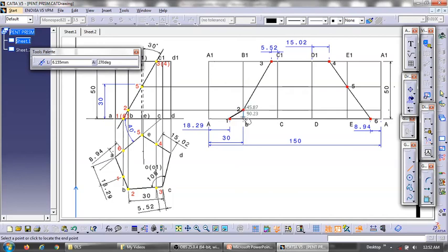So this is the truncated portion, and since all these portions of the vertical edges, that is 2 to B is also the remaining portion of the vertical edge BB1, that has to be darkened. Then C1 to C is a vertical edge that has to be darkened. D1 to D is a vertical edge that has to be darkened, and this 5 to E is the portion of the vertical edge E1E, so that also has to be darkened.